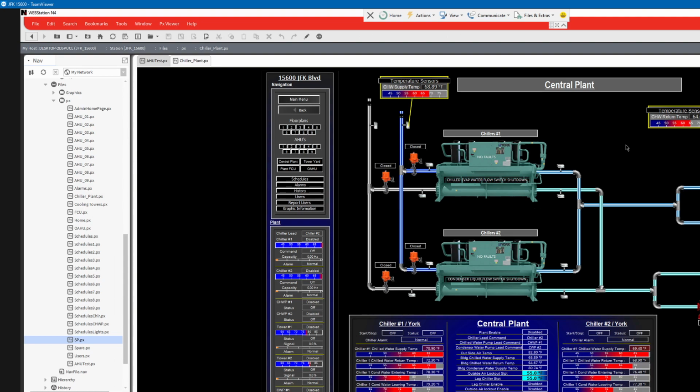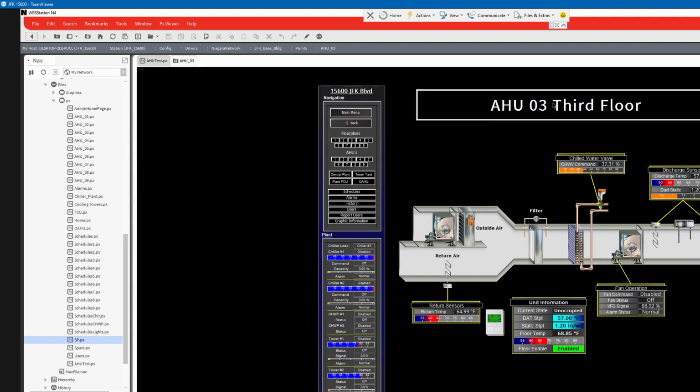And then you can also do a lot of different other things. Like I said, right here, I wish this site we had the VAV boxes built in. We're actually in the process of getting ready to start retrofitting all the pneumatics to DDC for this particular site.